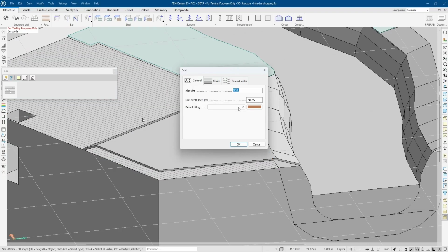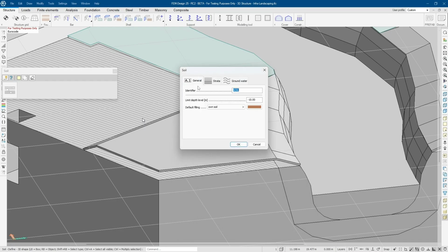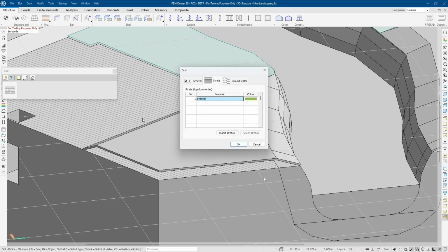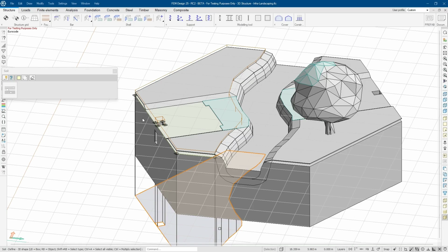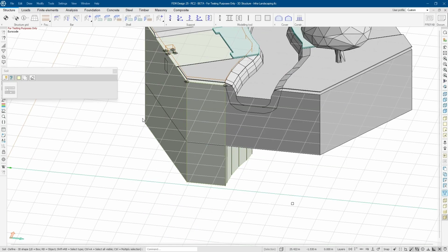Let's see what happens if I click here. I try to make this a soil. I just put simple friction soil like gravel here, use the same here and set one groundwater level like that. And you can see it just takes one region because it's not continuous, so it probably does not work. But if you select all of those plates, maybe it works. But let's see it the other way.